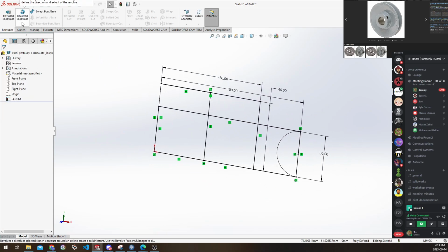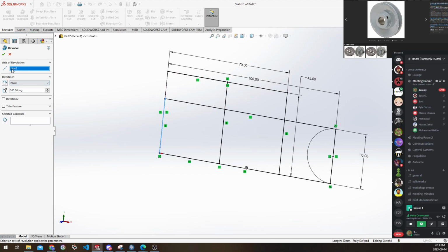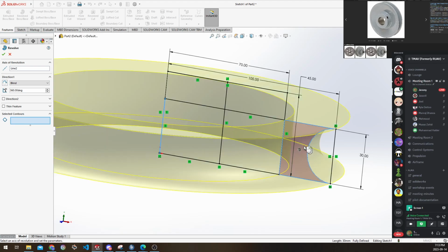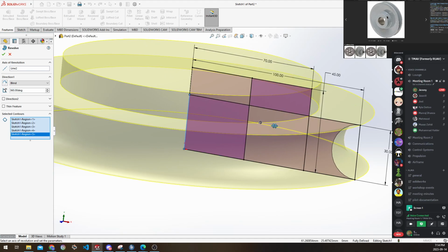There's revolve up here. Click on the axis of revolution. This line extending from our origin here is going to be our axis of revolution. And we're going to select those same contours. Okay, we're going to make sure to...